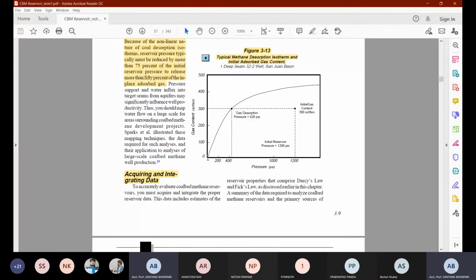as received moisture. Now, suppose you are going to prepare the dry sample. By the standard process, there are standard processes, you are going to prepare the dry sample from that coal. And then you are going to test the sample. You will find that in the dry sample also there is 1.5% of moisture available. The sample is not totally dry. So what does it mean? From 5% to 1.5%, this 3.5% of the moisture was the mobile moisture.